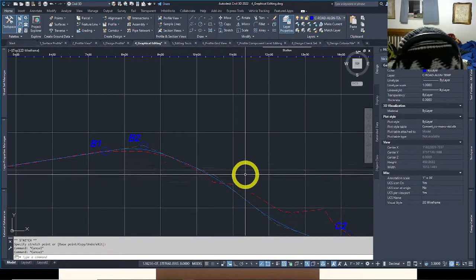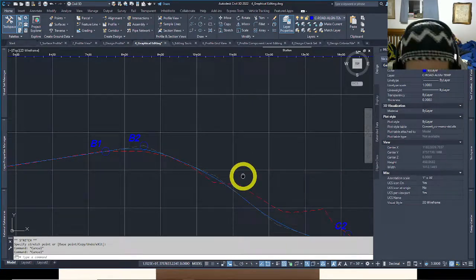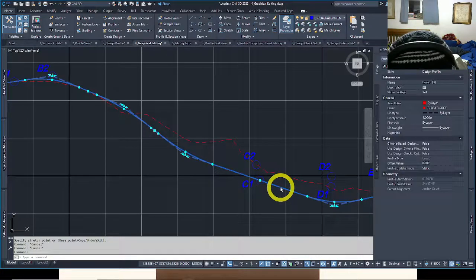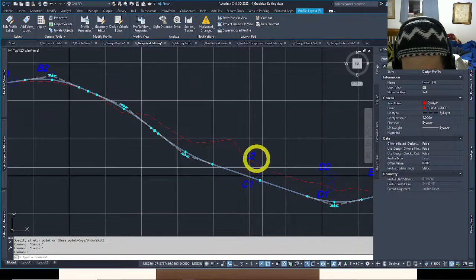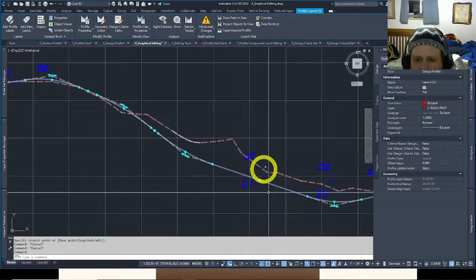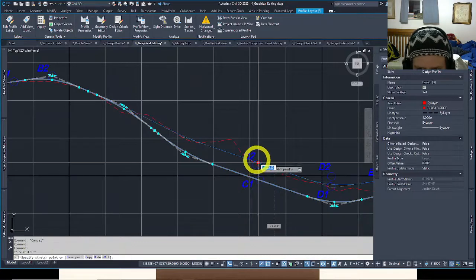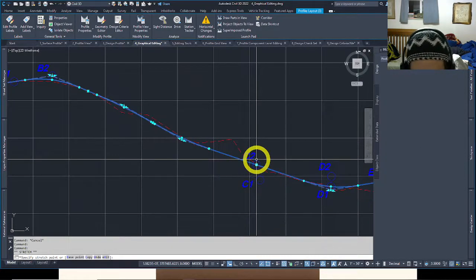If we go to page 138, we'll move to C1. Let's click our design profile again. In this case, we're going to take the middle of this tangent line. We also have a square grip there. We can move those. So a lot of times you might do some drafting with circles and polylines, however you need to do to make a node to snap to. These ones just happen to be given to us, which is just for instructional ease. I can move that to the center.